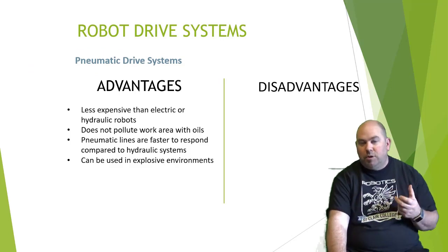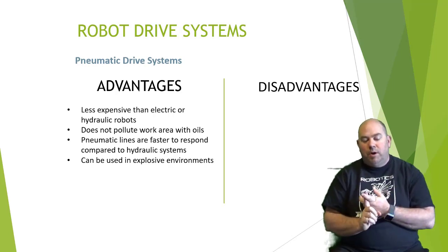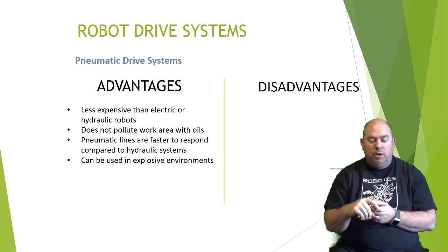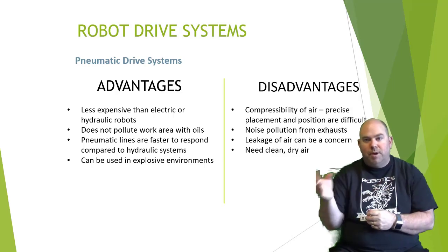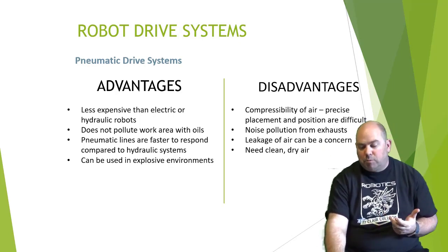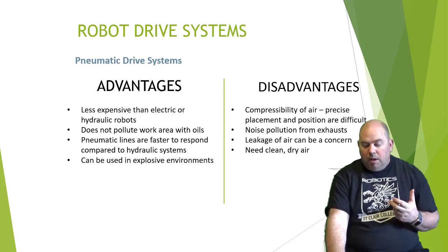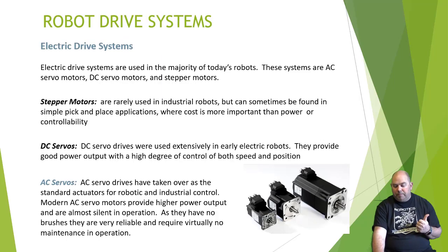Pneumatic systems. This is basically using compressed air to make things move. Things we like about pneumatic systems, very inexpensive to use. Don't pollute the area because there's no mess involved. You're just basically venting air out into the atmosphere. Can be used in explosive environments. Disadvantage of these, you need a clean, dry air source for them. Noise pollution from the exhaust, leakage of air can be a concern, things like that.